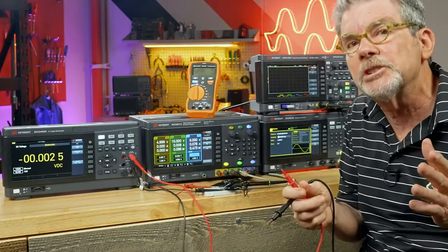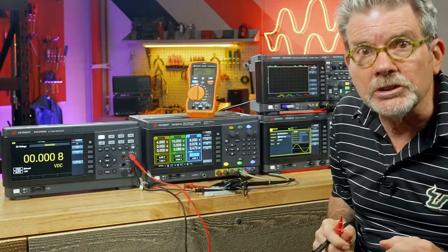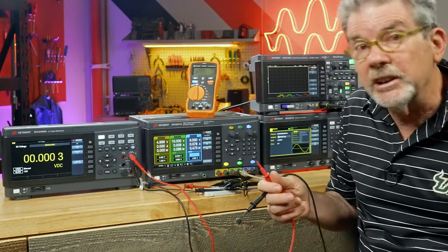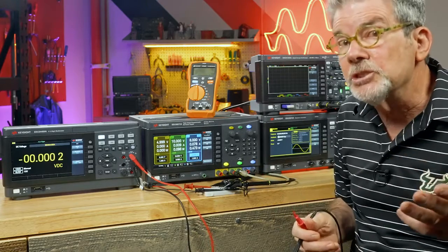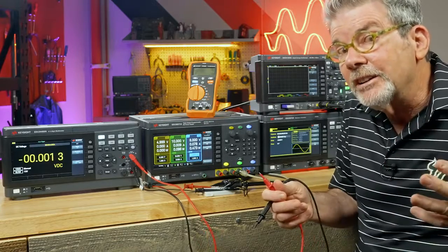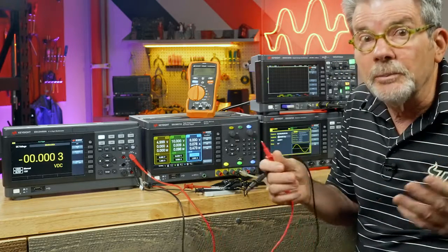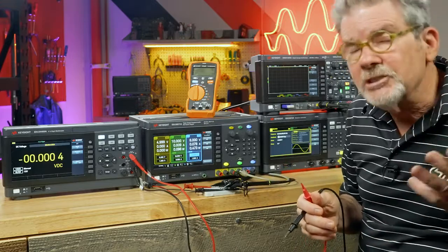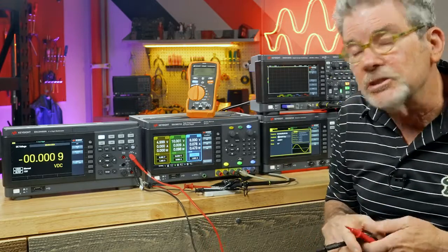But what if we'd measured 0 volts across R2, which might indicate a short? Or what if it measured 10 volts, the input voltage across the whole network? That might indicate an open, maybe something's burned out. So the next step might be to measure the resistance of my component.